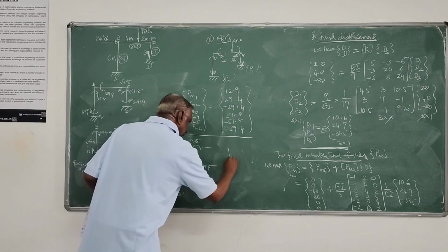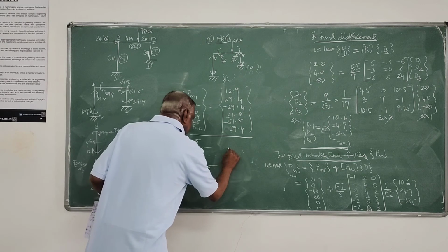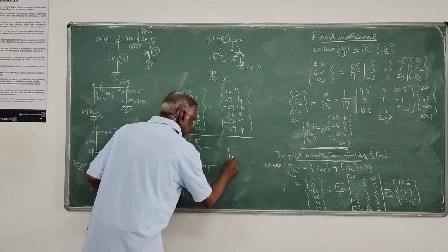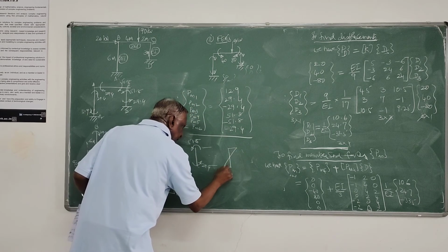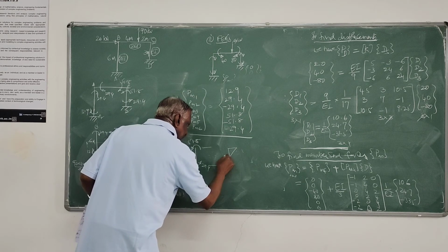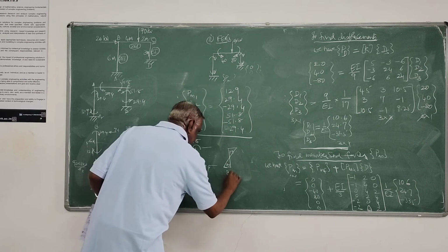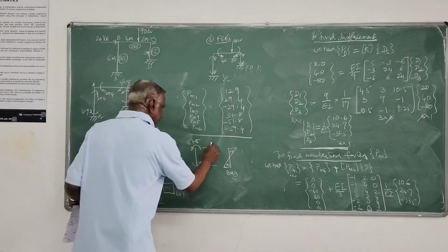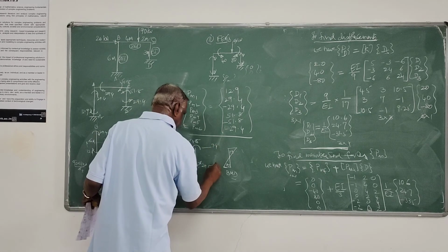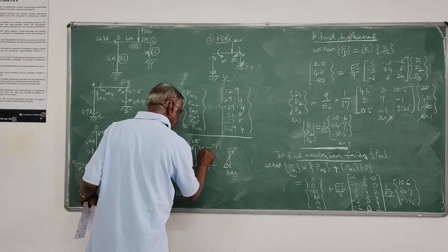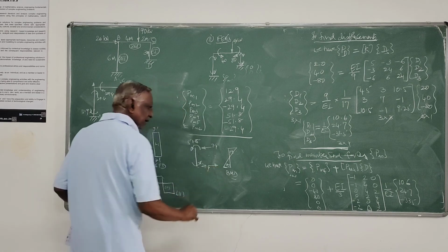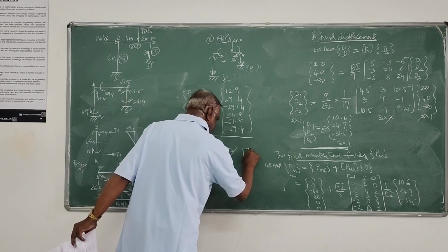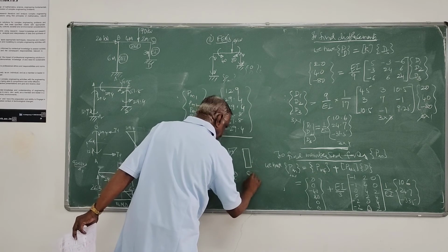So only the bending moment diagram we can plot. This side it is 51.8, 29.4. The bending moment diagram is like that. So this is the BMD and the shear value is 7.4. Whatever it is, this has to be 7.4. So if it is 7.4, it also has to be a rectangle.